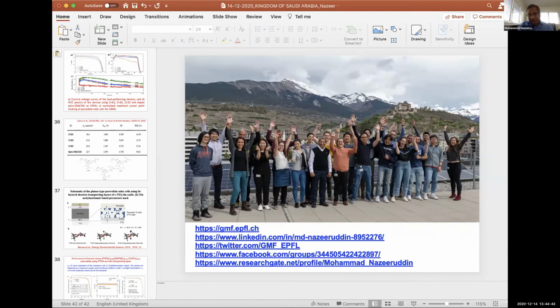So there are several techniques and several groups who are developing methods to get homogeneity of this material. For example, there is the blade coating technique. Spin coating is very interesting. At lab scale, you can produce up to 10 by 10. But if you want to go beyond 10 by 10, the spin coating technique is not viable because you lose a lot of material. The blade coating technique is one which is coming up, and slot die coating is also coming up. So these are the two large-scale applications. You can have uniform coating. And the new technique which several groups, including American groups, are producing is a spray type of deposition. So for uniformity, these are the 3 techniques which can be applied: spray coating, blade coating, slot die coating.